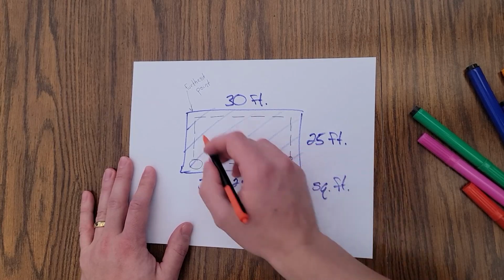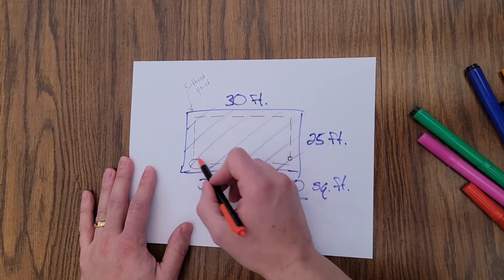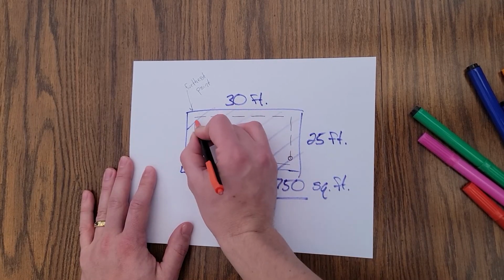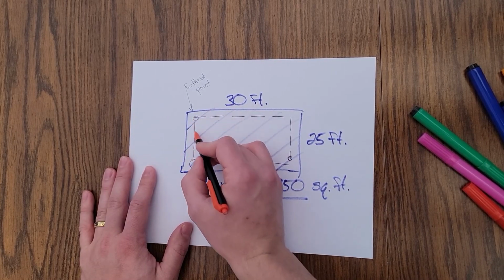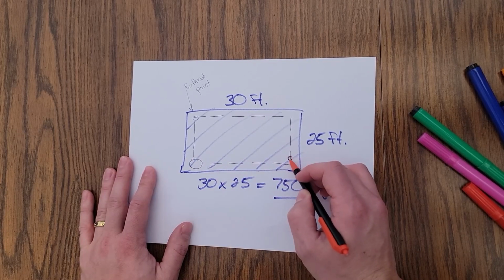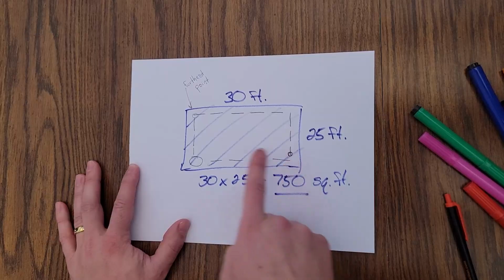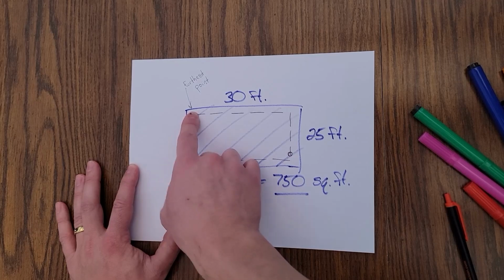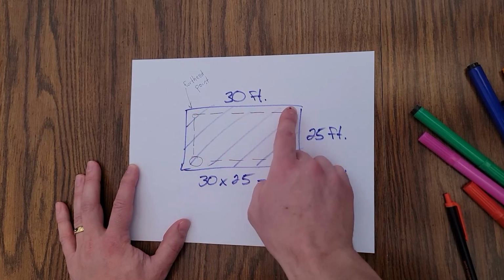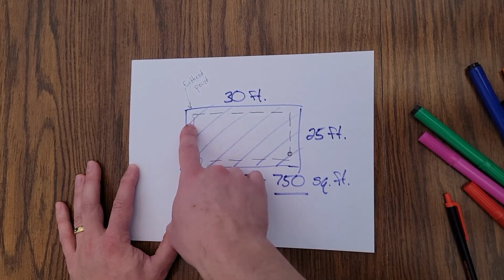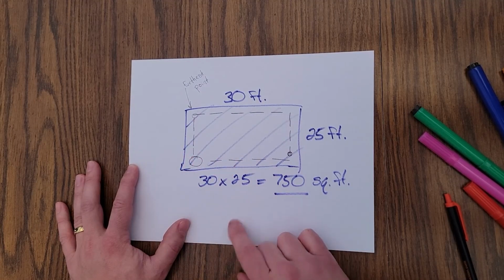So instead of taking all the length of piping, so this 30, 25, 25, the air is gonna travel from this point, and it's gonna go down and then out of the hole where the radon pipe goes through the floor. If we have enough power or force to pull air from this point, from this side, we'll have enough power or force to pull air from this direction as well. And so the total amount of added length is 25 plus 30 is 55.